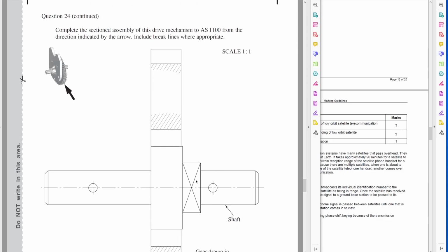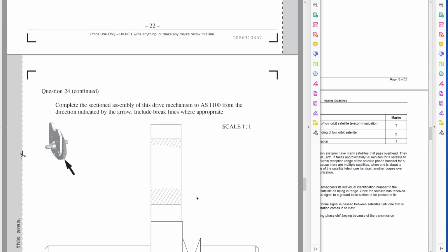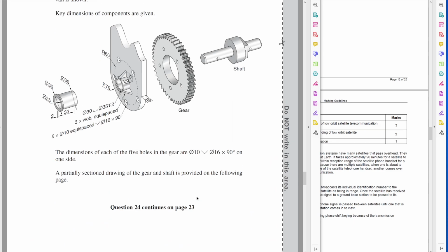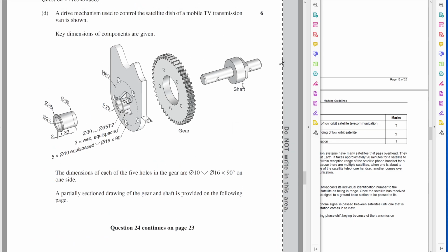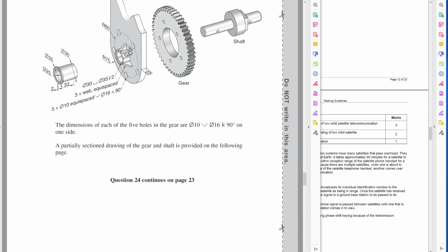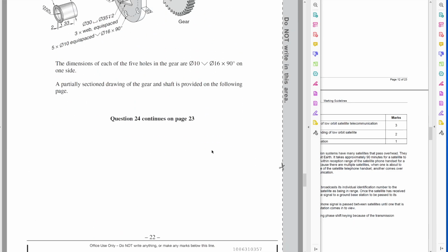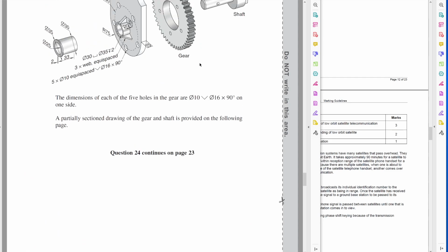Okay, so first of all, this X means that it's a flat, right? Just so that you know. They've done that for us to help us out, to say this area is flat. It means there's a section line, but we can ignore that; section lines indicate that there's a circular thing going on there. That cross says it's flat at that location. This here says that there's countersinking. So it means that we're drilling a hole and then there's going to be a countersink there.